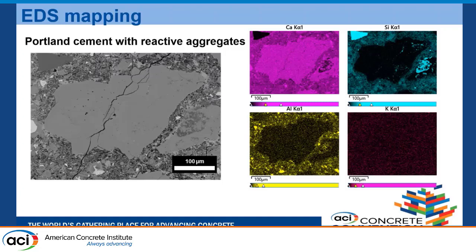The potassium that you see in the image is not an indicator that you have traces of potassium. You should have some maybe in the cracked regions or some spots. If there are some selective spots where you find traces, that means we can do more analysis and see the chemical composition. That may be an indicator of an ASR gel. So that is something I'll be doing. It's ongoing research, and that will be continued in the future.